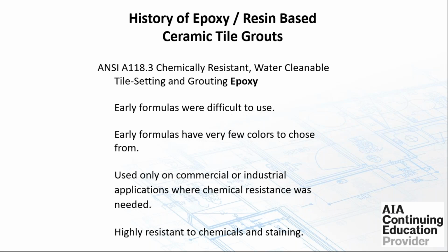The waterproofing has to start first. Epoxy, although it's a plastic, if you were to spread it out as a full uniform surface across an area, yes, it would hold water. But between the tile and the grout, you can still form a little crack or a little void. Water could get in there, and that could affect the waterproofing of your job. So epoxy grout is not a waterproofing. Waterproofing starts before you start the installation of the tile. Keep that in mind. It's crazy to get those questions, but they do come up.